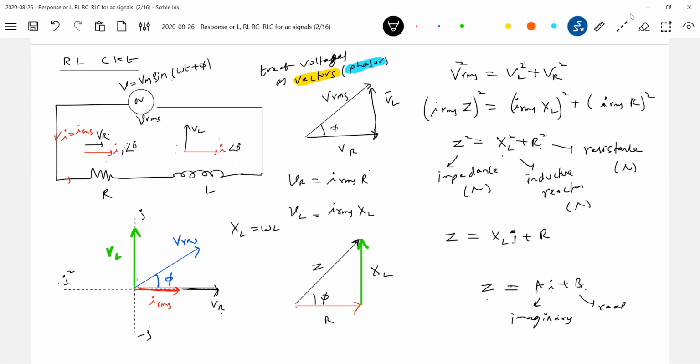Okay, I'll come out of that. That i is called the operator. So shall I call j the operator? So what is the operator? j indicates a phase angle of 90 degrees. Minus j, minus 90. j square, 180 degrees. So there's one representation and we call this a phasor, having magnitude and a phase angle. Z bar, if I call it, is considered a phasor.